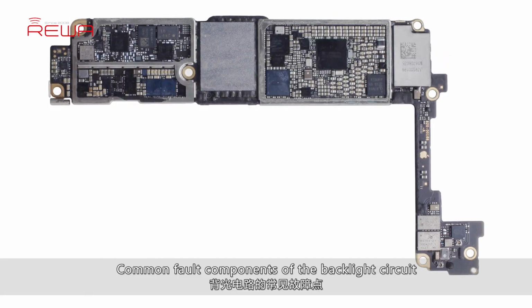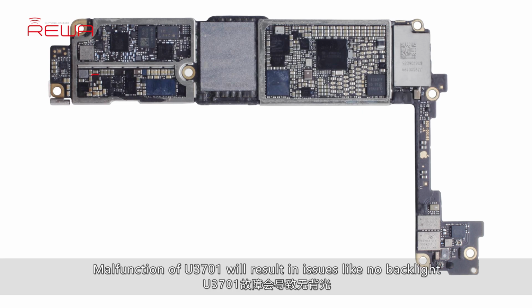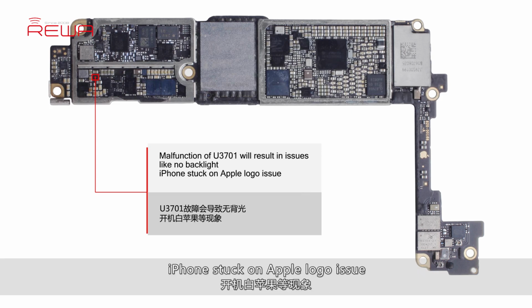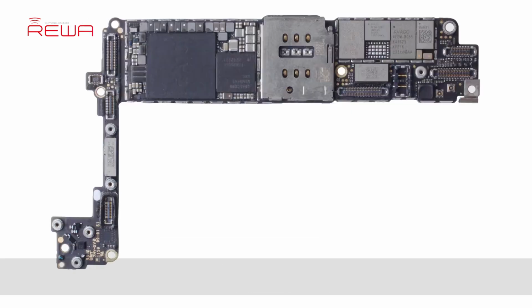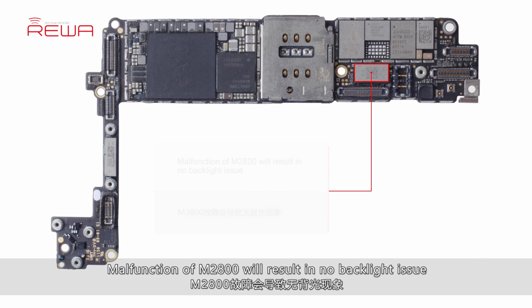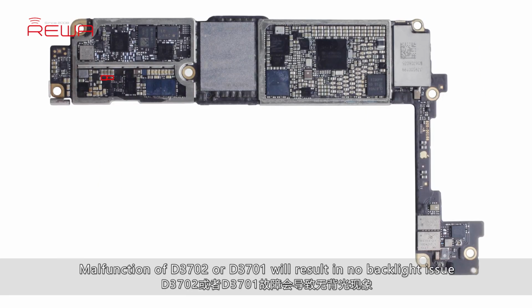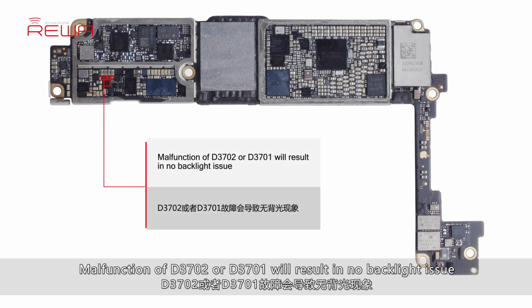Common fault components of the backlight circuit. Malfunction of U3701 will result in issues like no backlight, iPhone stuck on Apple logo issue. Malfunction of M2800 will result in no backlight issue. Malfunction of D3702 or D3701 will result in no backlight issue.